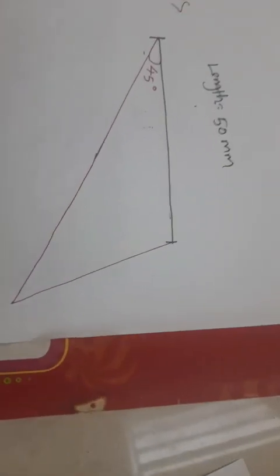Now I am going to split this line into, for example, 7 equal parts. If I am going to divide this line into 5 equal parts, I can easily mark 10 mm, 10 mm. But I am going to divide this line into 7 equal parts. This is applicable to your conic curves also.